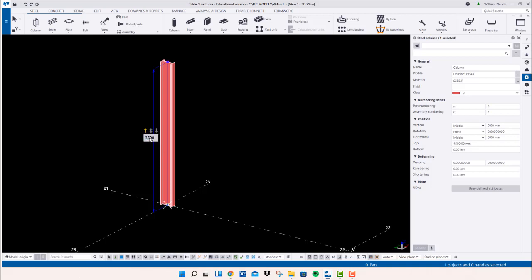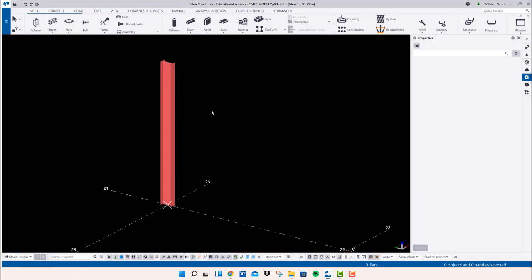So now, in total, what will happen is this top part will drop down by a meter if I press enter. So I'm going to press enter, and it dropped. So my total height is 3.5. Now, I'm just going to press Control Z again, just to undo.